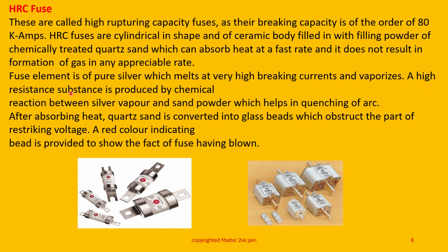A high resistance substance is produced by the chemical reaction between the silver vapor and sand powder, which helps in quenching of the arc. After absorbing heat, quartz sand is converted into glass beads, which obstruct the path of restarting voltage.